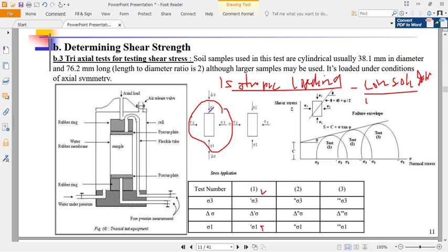This amount of water which goes out of the sample when you apply the symmetric loading, or what we call the confining stress, will be equal to the volume reduction of the sample. Is that okay? The volume of water which you collect here will be equal to the volumetric deformation which has occurred. Is that okay? But if there's no consolidation, therefore the drainage lines are locked and the sample is saturated, therefore this material cannot deform. Is that okay? The material cannot deform.